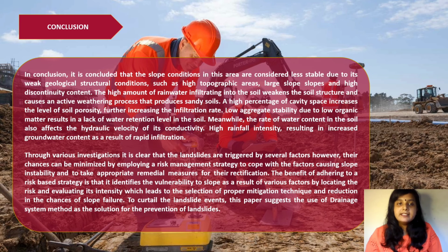Conclusion. In conclusion, it is concluded that the slope conditions in this area are considered less stable due to weak geological structure conditions, such as high topographic areas, large slope, and high discontinuity content. The high amount of rainwater infiltrating into the soil weakens the soil structure and causes an active weathering process that produces sandy soils.